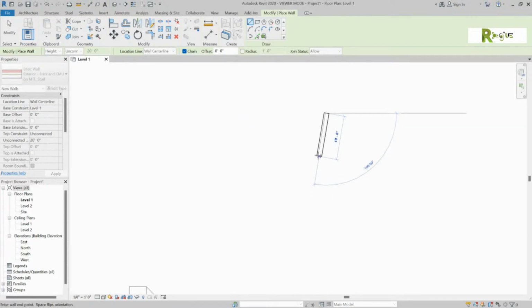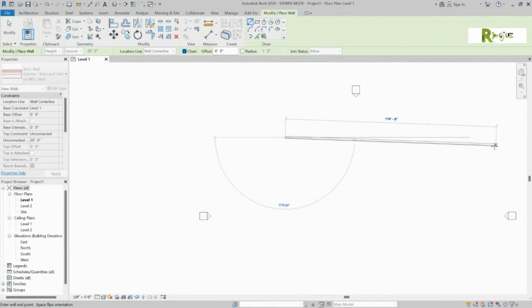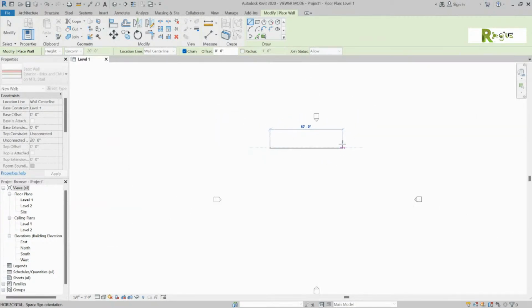Okay? Now, generally, if I'm going to be drawing a brick wall, I would want to set my units so I'm snapping to every 8 inches so that things stay in coursing. Right now, at that certain zoom level, you're going to be snapping to, see right now it's snapping every 2 feet. Zoom in, and you'll find that it starts snapping. Now it's snapping every 6 inches. So if you were doing a brick building, it would really benefit you to change that from every 6 inches to every 4 inches. And I will show you how to do that probably middle of next week. Okay? But hit your space bar and then draw a shape of a building.